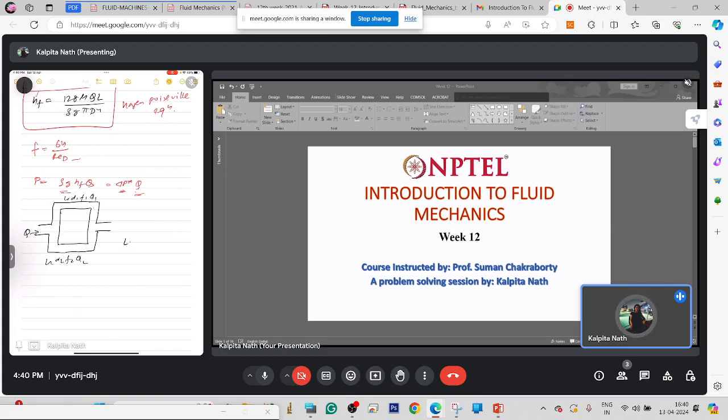Now L1 is equal to L2, F1 is equal to F2, D1 is equal to 3 centimeter, D2 is equal to 6 centimeter. Now hf1 is equal to 0.64. So what is hf2? Obviously, since the head loss remains the same in a parallel connection, in this half and this half, the head loss will be the same. So hf2 will also be 0.64. Any doubt?